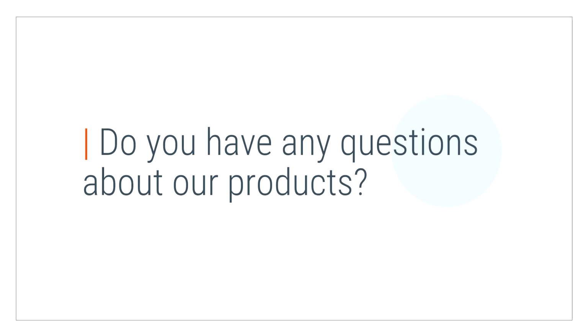Here is one question: where do you recommend to install the CO2 and VOC sensors in relation to the bottom of the room? I think Martin can answer this. The best thing is to have it at 140 centimeters from the bottom, so it's nearly in the middle of the room, and there are the best measurement values.